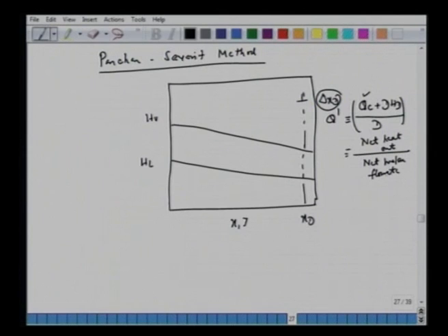So what is this net molar flow rate? Nothing but D, where D equals g n plus 1 minus l n. So at any plate, the vapor flow rate g n plus 1 and the liquid leaving l n, the difference is the same as your top product. So this is the net molar flow rate, net heat out. Of course the stream leaving is D, but we also included the condenser load here, q dash. So we mark this point.